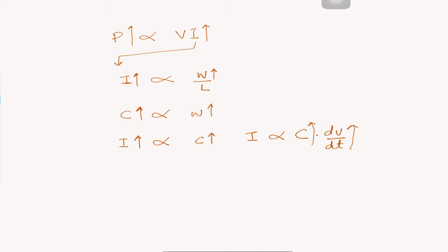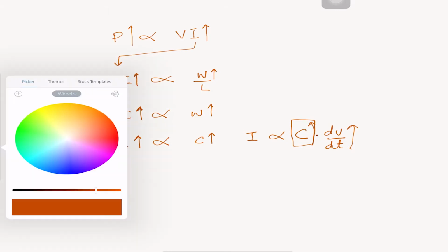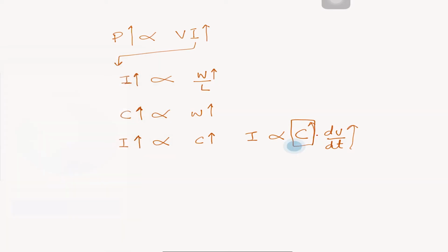This takes us to let's spend some time on the capacitance. Okay, what are the capacitances in a transistor? It's typically said in physical design that overall your transistors are getting bigger, you have bigger standard cells, and as a result there will be a bigger capacitance on the nodes, and when the capacitance is bigger, your current will be more, and when the current is more, your power will be more.